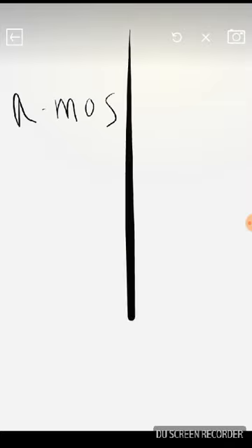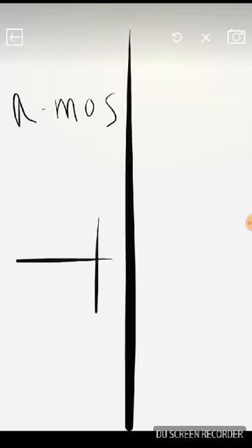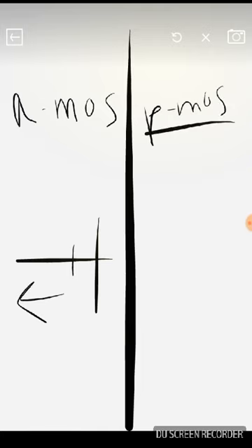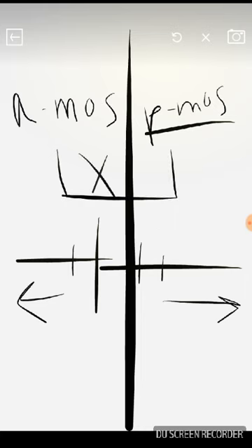So we can see that an NMOS works when the input is less than VDD minus VTH, whereas a PMOS works at an input greater than VTP. So if these two work separately, they are not able to serve the entire region.